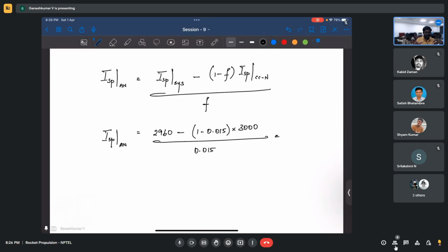If you do a serial connection, it will have a higher resistance. When you do a parallel, it comes down, right? You can think of it in that manner also. You just divided the mass flow rate. That's all. Okay. Face that penalty. Instead of giving it to a highly efficient system, you gave it to an inefficient system. So that penalty is what we see in terms of ISP. The overall ISP of the system goes down.